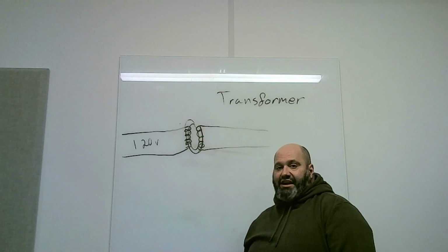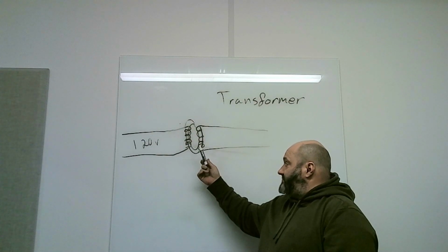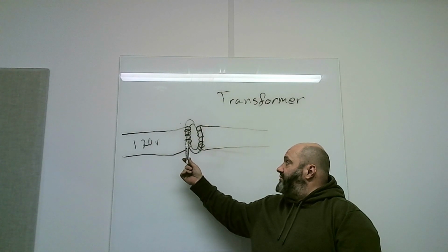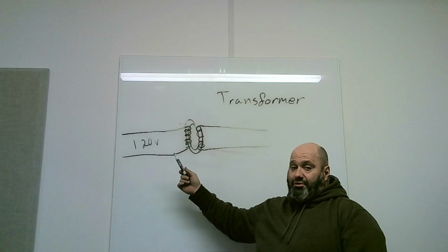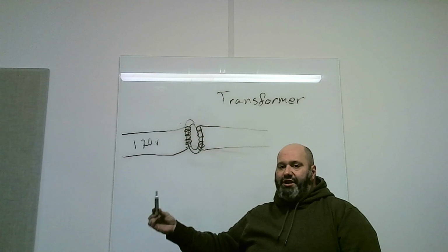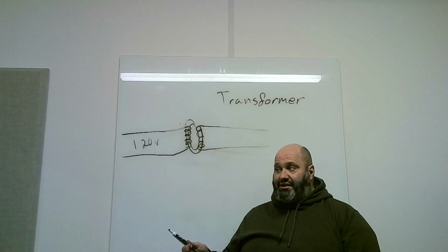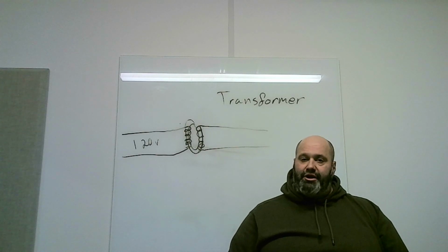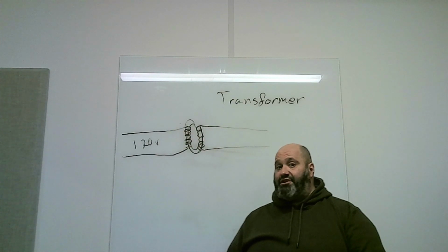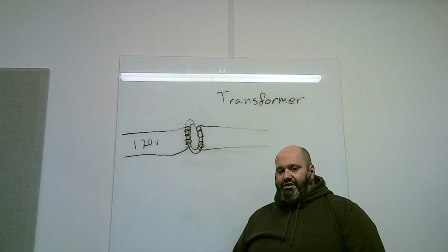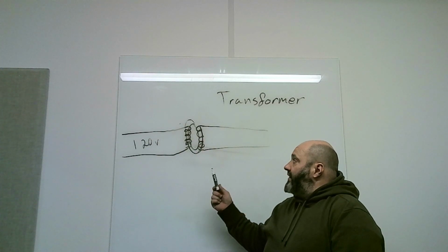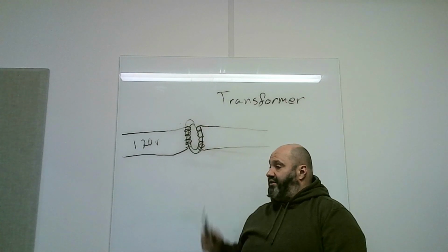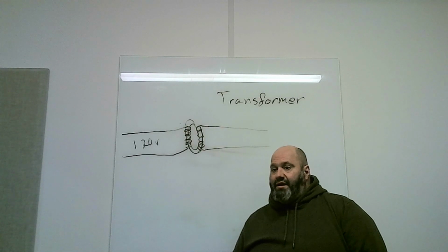One of the simplest tests is an ohm reading. Obviously, you want your power to be cut to the transformer, and ideally, you want it connected to nothing. You can get by without disconnecting it completely, but personally, I prefer to disconnect everything from it. That way, you are truly isolated. You should get a low measurable resistance reading off of a magnetic induction coil.